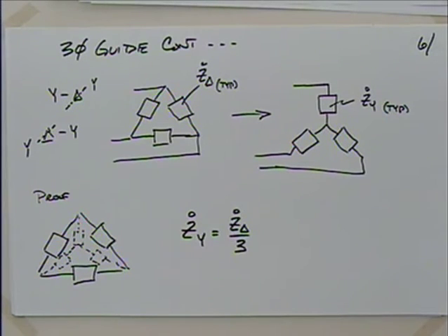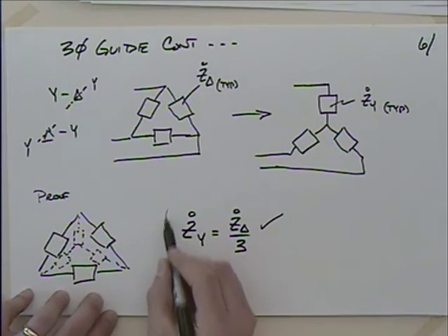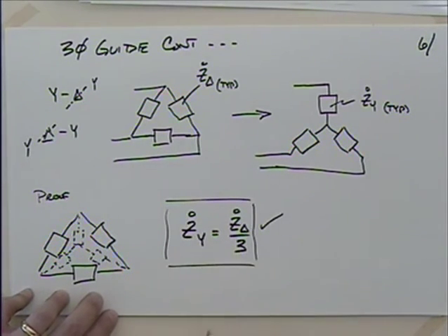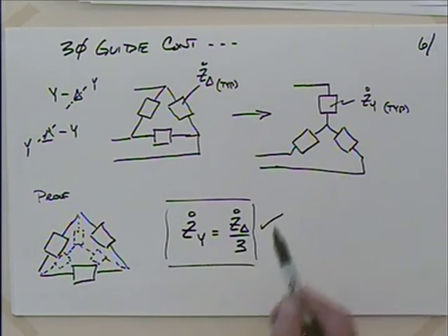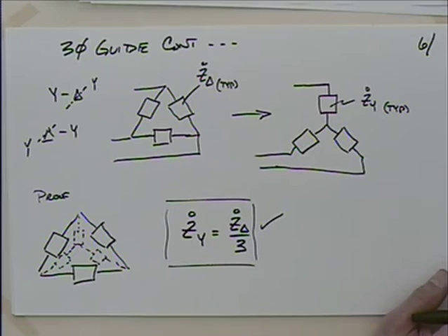But remember back when they were all resistive, and you had those resistor values, if you make all the resistor values exactly the same, you will see this 1/3. Okay, so there's nothing really new there. Well, that's a powerful tool when I want to convert my delta to a Y. For instance, if you have an impedance here that's delta and you want to get it to a Y, you just take those impedances and divide by 3. We can go the other way if we want to. It's probably more common to be dividing the deltas by 3 and turning them into a Y.